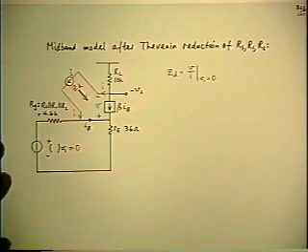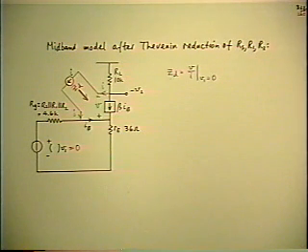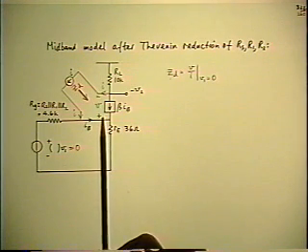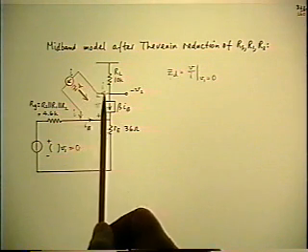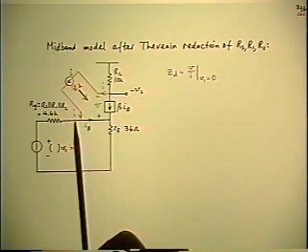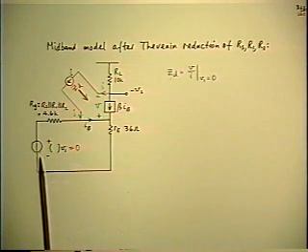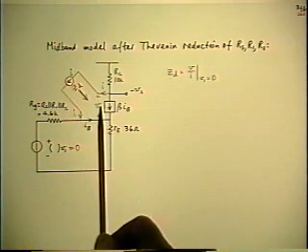Okay, let's set out to calculate the ZD, or in this case the RD, because the reference circuit is resistive, so we know we're going to get a resistive value of the driving point impedance. Okay, the condition is we apply a test signal across the two terminals where the extra element is going to be placed, and we make the input 0, and we calculate under single injection conditions what the driving point resistance is.